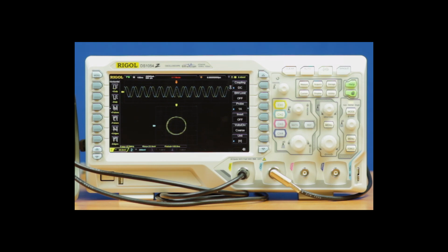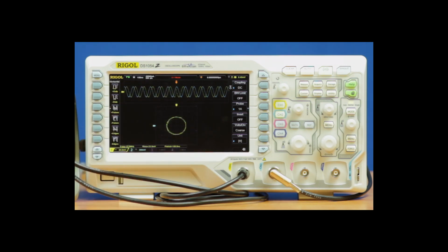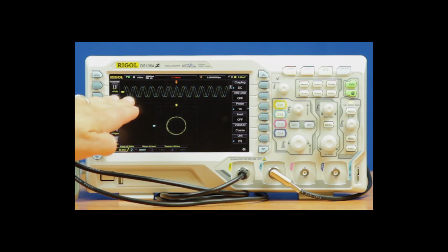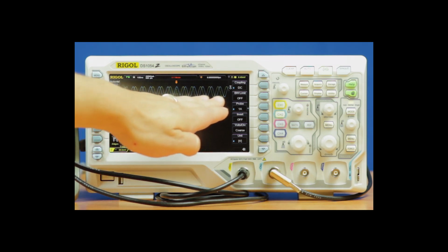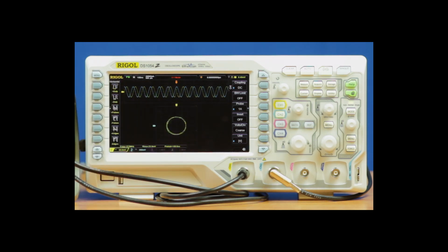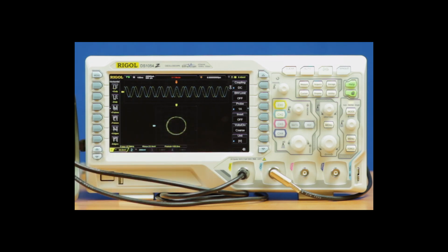So each of those makes a curve. And we can see at the top of the screen our 180 degree phase transition that we talked about before in channel 1 there, where it switches. And so you can see in the left half of the screen, the blue is leading by 90 degrees, and then it switches. And then on the second half of the screen, the yellow trace is leading by 90 degrees. But because we're always offset by 90 degrees, both of those symbol patterns result in a circle on our XY graph. So that's a great way to look at 2 signals 90 degrees out of phase.